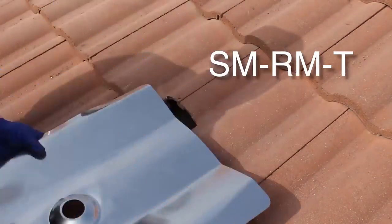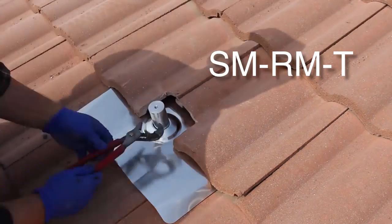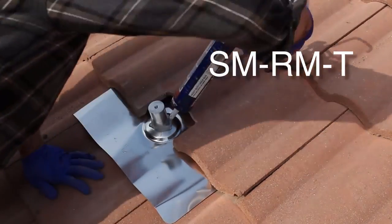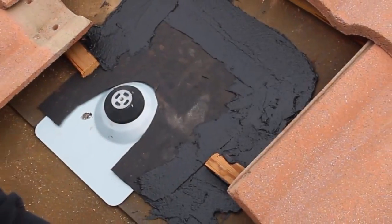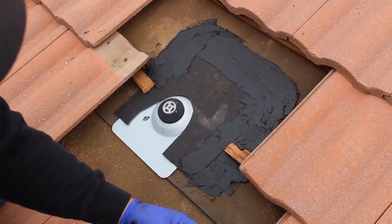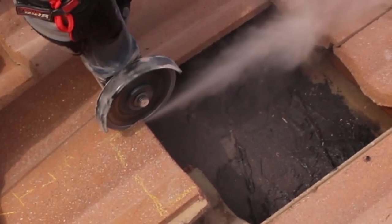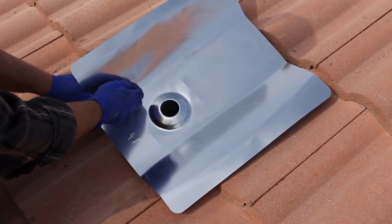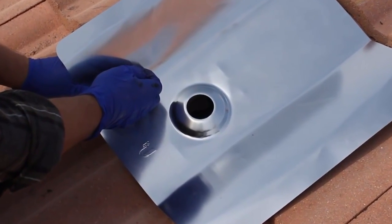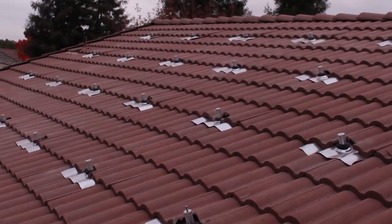Once shaped, slide the tile flashing underneath the tile, then securely install the extension post before applying roofing sealant and seating the rubber cap. To review, after the roof mount and flashing are installed, proceed to measure and cut an area in the tile roof through which the roof mount will protrude. Once cut, place the tile back into position, then shape and fit the tile flashing to fit the contours of the tile material before installing the posts with roof sealant and the seated rubber cap.